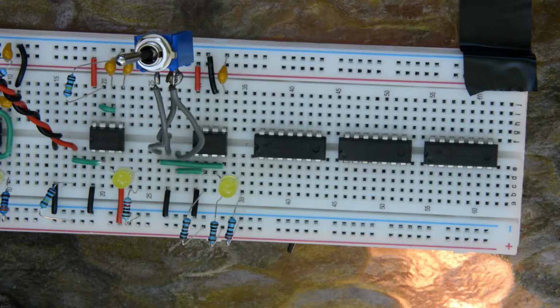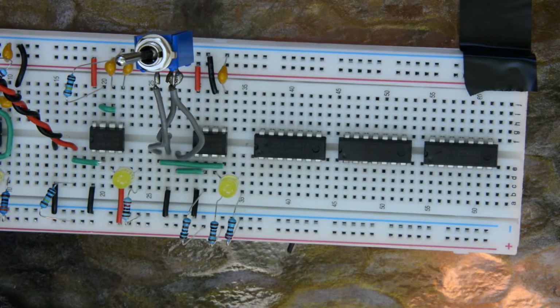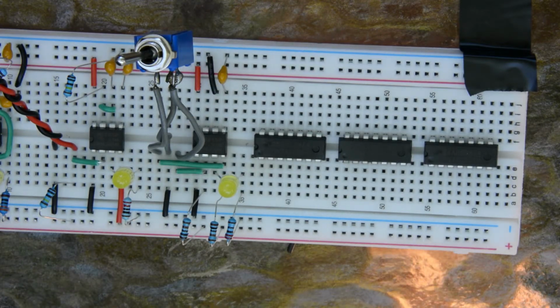And then the same thing for our AND gate. This is the 74LS08, and you can see it's got power and ground, and then it's got the 4 AND gates. We're only using 3 of them on there. So if we follow this through just to make sure it all looks right, the output of our select here, so when we push our select button, that output, of course, is on pin 3.